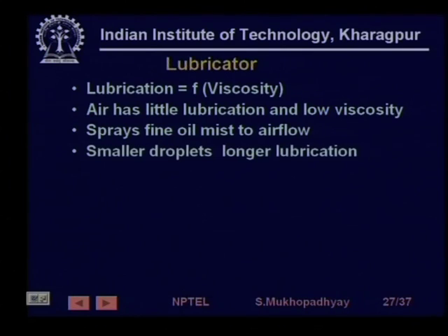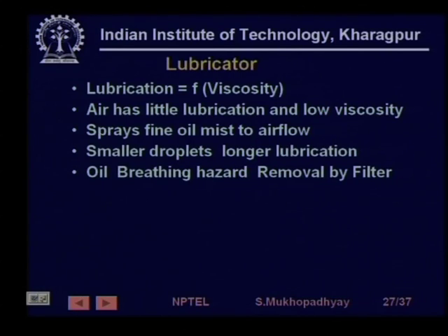Therefore, the lubricating oil is in a kind of atomized form. It is spread into the airflow, and then the airflow takes it to various points where it provides the lubricating function. If you have smaller droplets, you have longer lubrication. But remember that the moment you put in this oil mist, you cannot directly release the air.